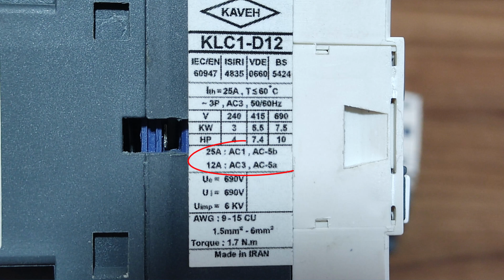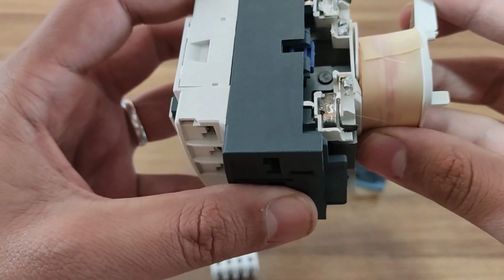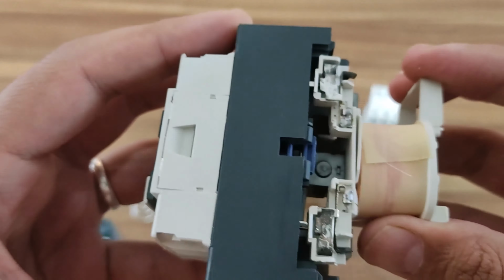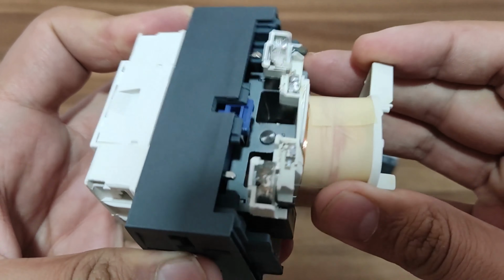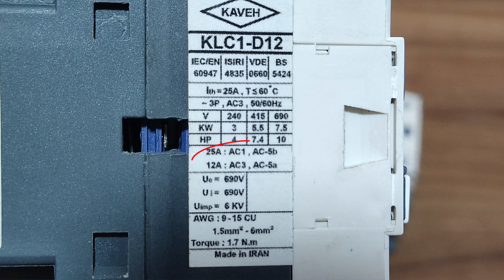4. Rated working current. It is a current that is provided by the manufacturer considering the contactor's operation specifications, and the contactor is designed for continuous operation at that current. 5. Nominal thermal current. It is the current that the contactor can withstand in the closed state, in open air, for 8 hours without its temperature exceeding the amount mentioned in the standards. 6. Working group. The IEC standard divides contactors into different categories depending on the application and the place of use, which includes both AC and DC contactors.